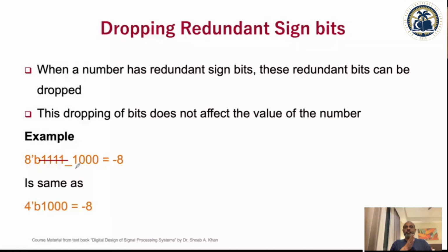Let's say your number only varies from -4 to +4, but you have 12 bits to keep it. All the time you are going to see 11111111, because your dynamic range is so small that your number basically does not require 12-bit or 16-bit precision.